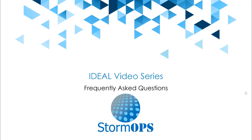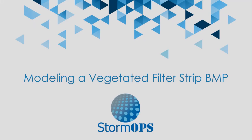This is a series of short videos to explain how to approach common scenarios, model specialized BMPs, or troubleshoot typical issues. Today's video is about modeling a vegetated filter strip BMP. The vegetated filter strip, or VFS, is a BMP commonly used as a pre-treatment for other BMPs and by itself. When the vegetation is dense and the slope is mild, these BMPs can achieve excellent trapping of pollutants. Most VFSs are grassed, but we will also look at the new option to model existing forested buffer areas as vegetated filter strips.